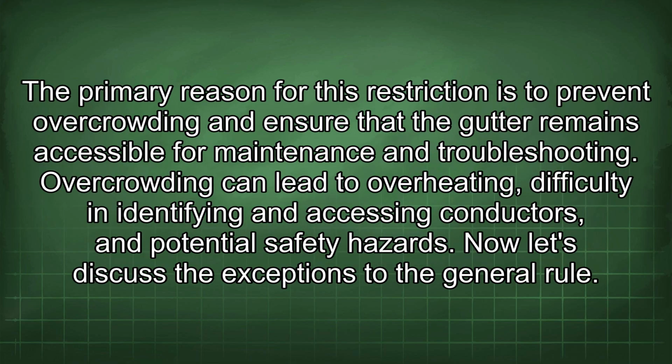The primary reason for this restriction is to prevent overcrowding and ensure that the gutter remains accessible for maintenance and troubleshooting. Overcrowding can lead to overheating, difficulty in identifying and accessing conductors, and potential safety hazards. Now let's discuss the exceptions to the general rule.